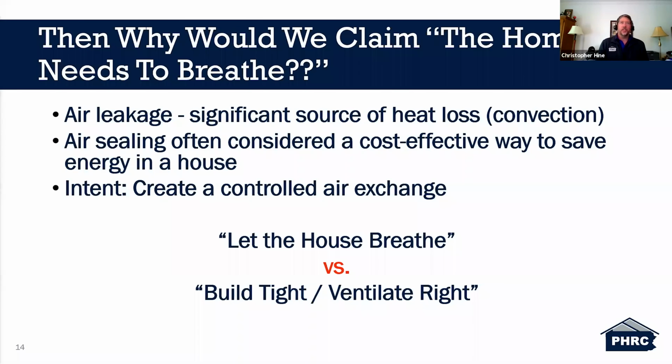So then I asked the question, why do we claim that the home needs to breathe, right? I've heard that saying many, many times. Well, we're building the homes too tight. They need to breathe. But air leakage is a significant source of heat loss through convection, through air movement, right? When you have air movement, you're going to have the conveyance of heat moving with that, through convection. And air sealing is often considered a cost-effective way to save energy in a house.